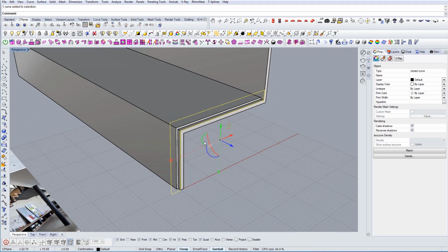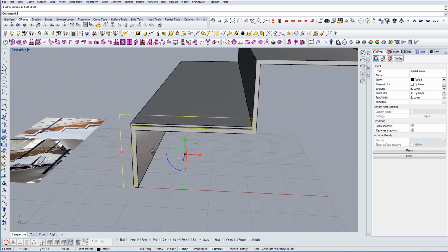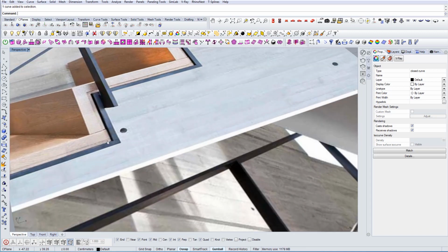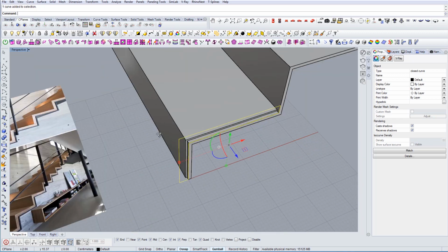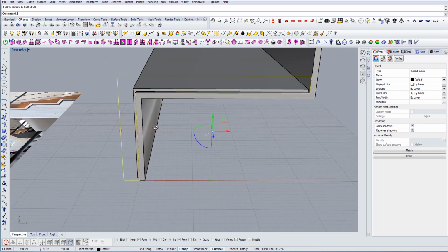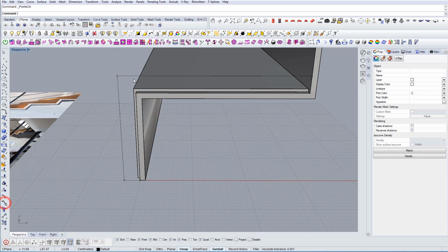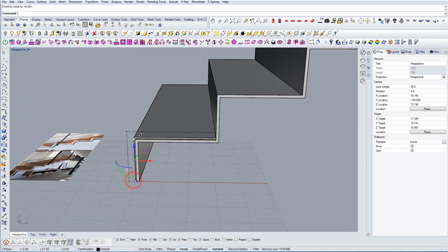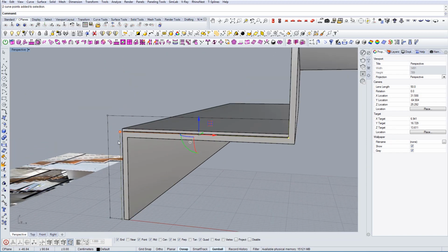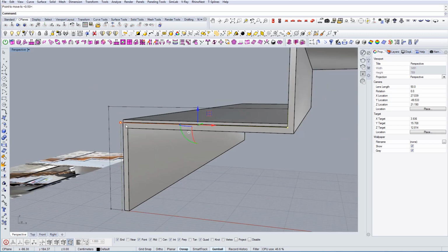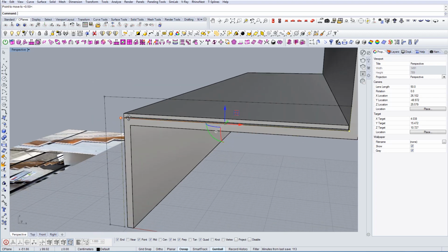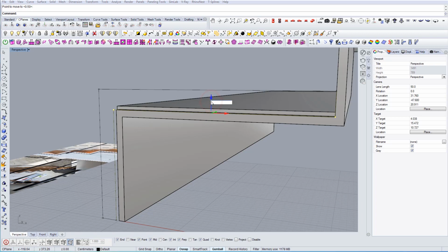As you can see here, since in the reference image it shows that it's actually extruded, so I think it's in the same plane as this black one. So I'm gonna use just quickly control points to move them till there, and here until there. I can use 0.5 to move it. And now let's extrude it.